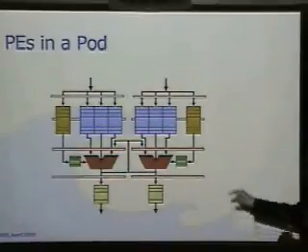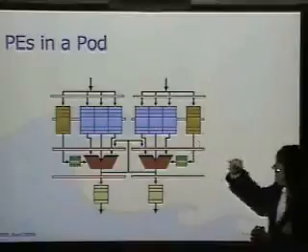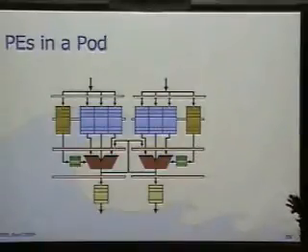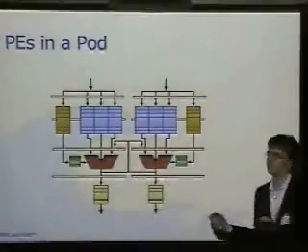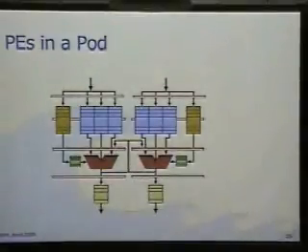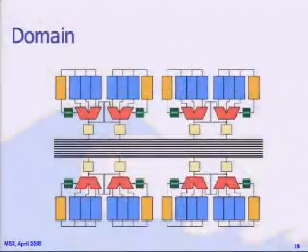Within a pod, the two processing elements are completely disjoint, except that their bypassing networks are conjoined. And what that allows us to do is get back-to-back execution of dependent instructions within a single pod, and that turns out to be pretty important for overall performance.